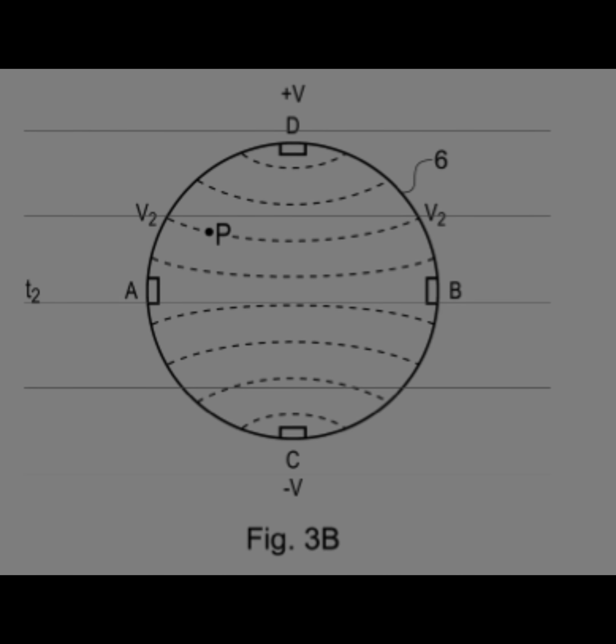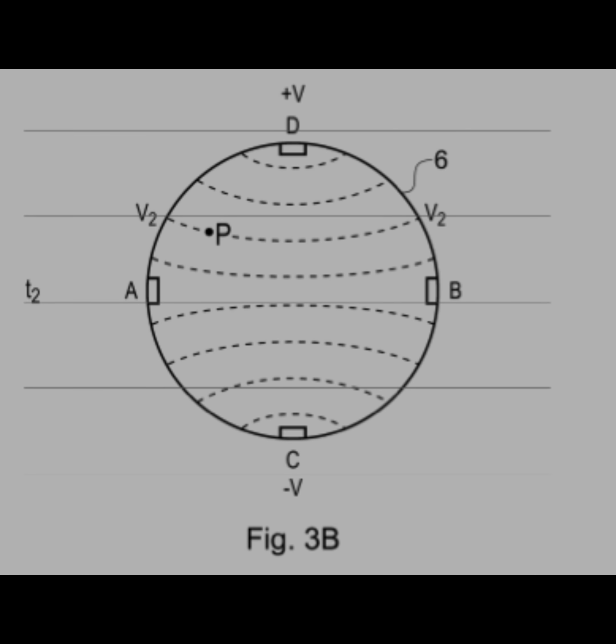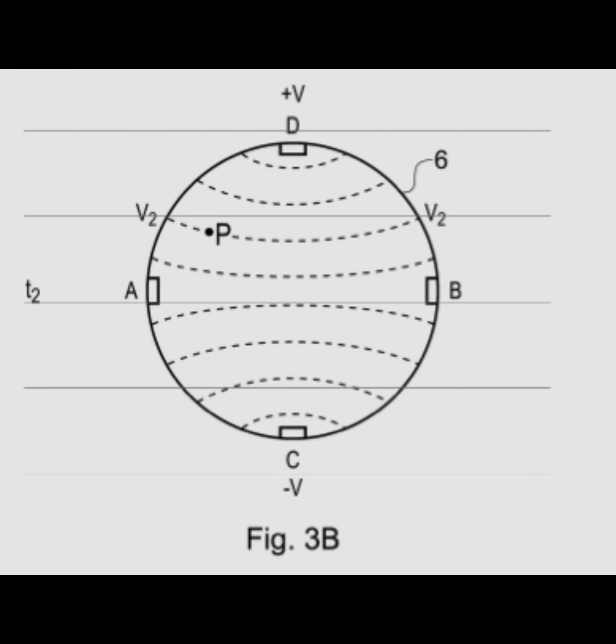The panel 201 has a rigid support 202 made of electrically insulating material. A conductive layer 208, an electrically insulating gel layer 207, a resistive layer 206, and an electrically insulating protective layer 205 are provided on the rigid support 202 in this order. Each of the layers is continuous and covers the entire support. The resistive layer 206 and the protective layer 205 are relatively thin so that they deform when pressure is locally applied to the panel 201.